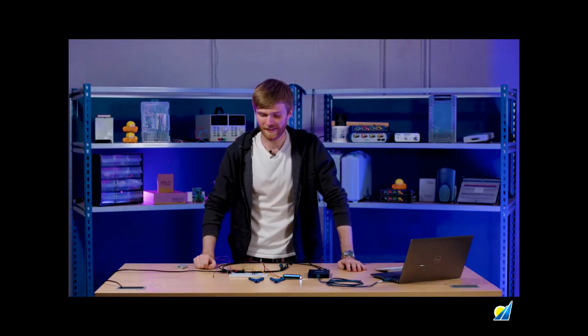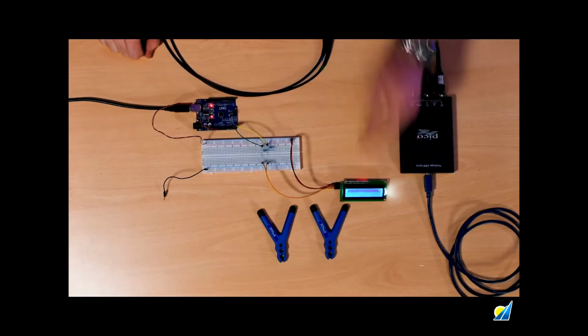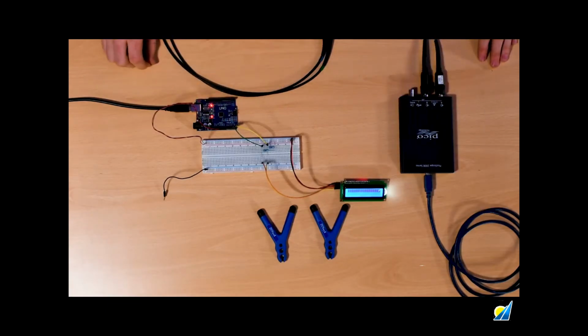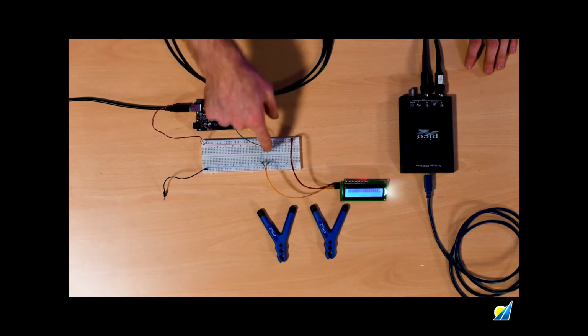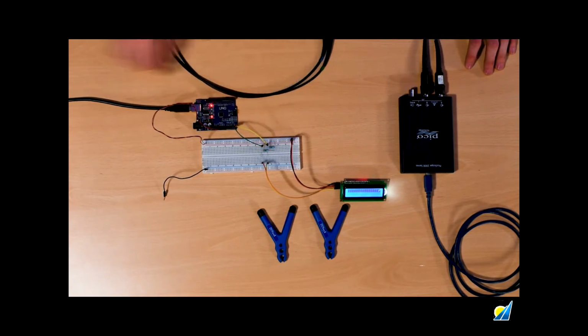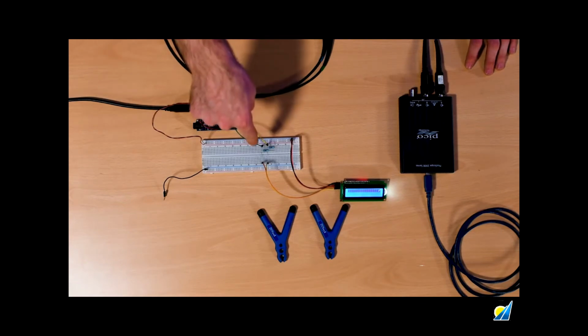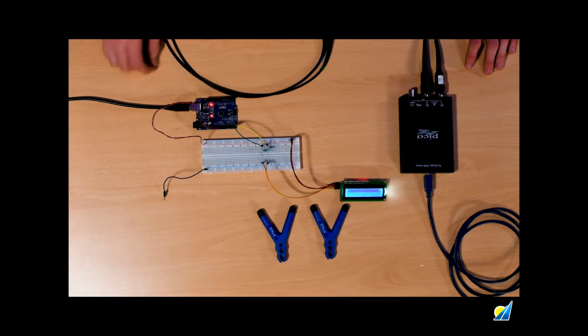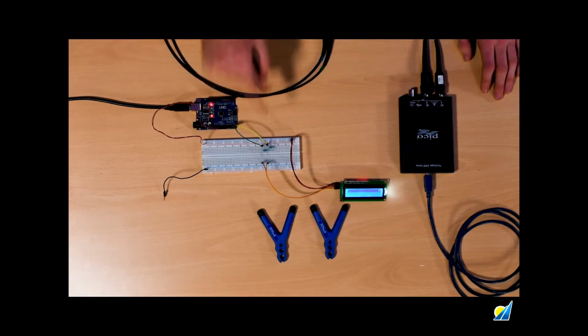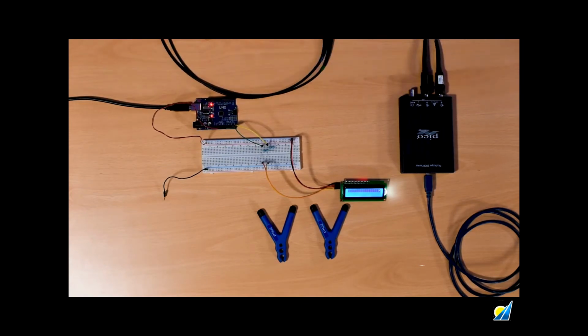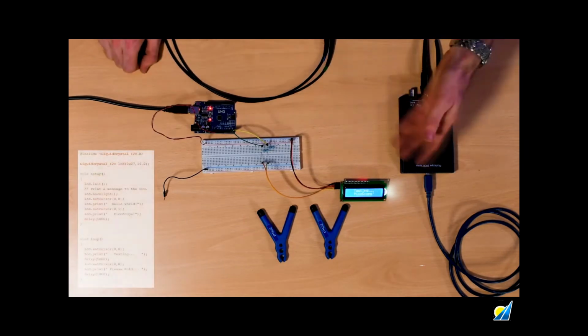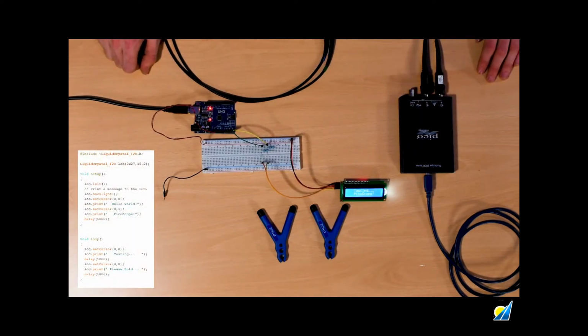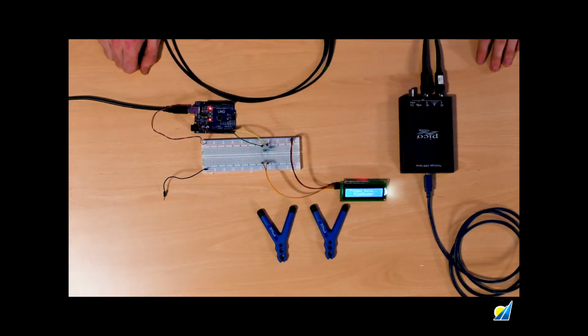So what we have here is we've got our Arduino and our LCD, and they're both powered by the Arduino. So with the I2C, we've got two 4.7Ks which are pulling these two SDA and SCL lines high. So the green and the orange is the SDA for continuity, and the yellow is SCL. On the Arduino, we have a simple script which is just going through some quick messages, sending them to the I2C on the back and populating it onto the front of the LCD.